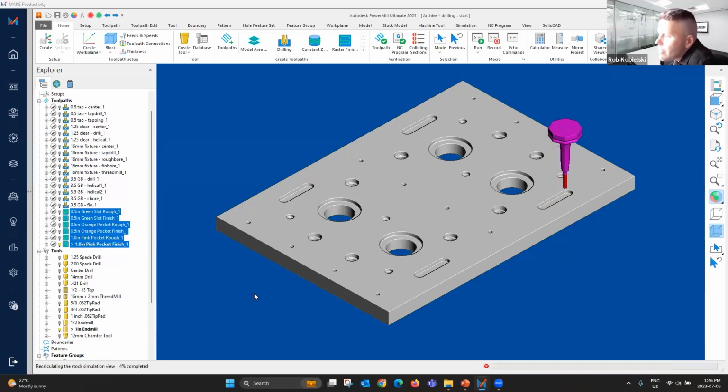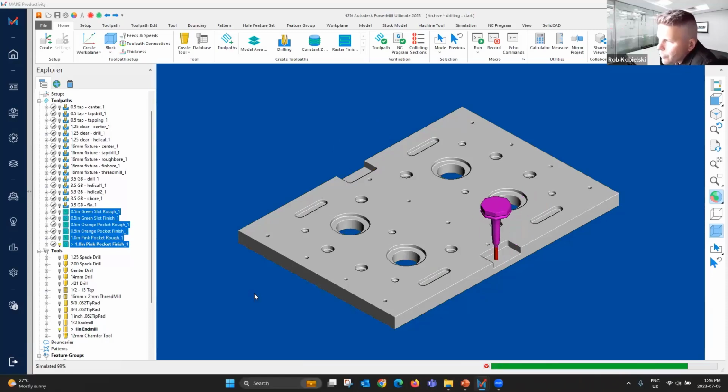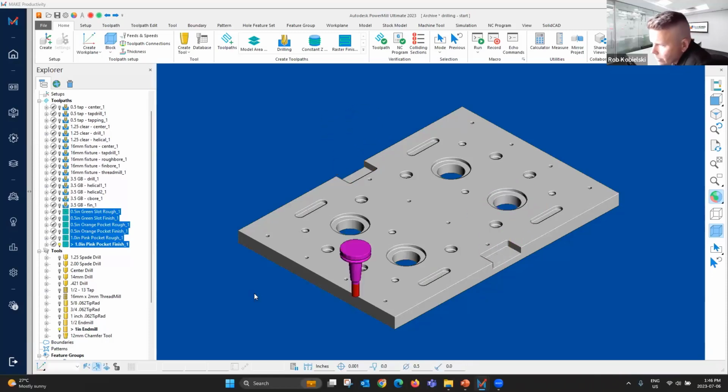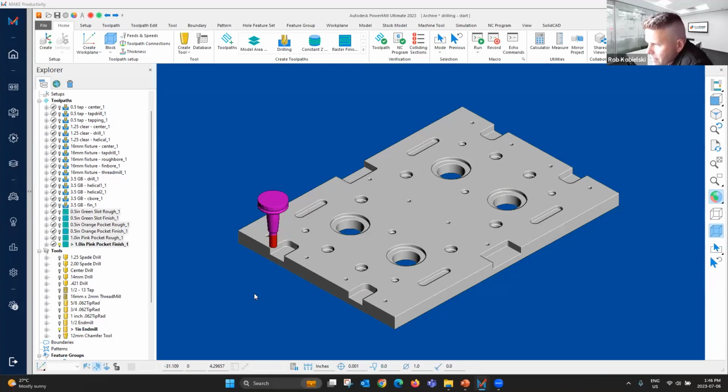Okay. The style of milling is completely personal preference. When I created the programming standards for these slots, we opted for a full flute depth of cut, as opposed to the more traditional approach of a small depth of cut and large step over. But again, this is personal preference. You have full control and full autonomy of how you build these programming standards.